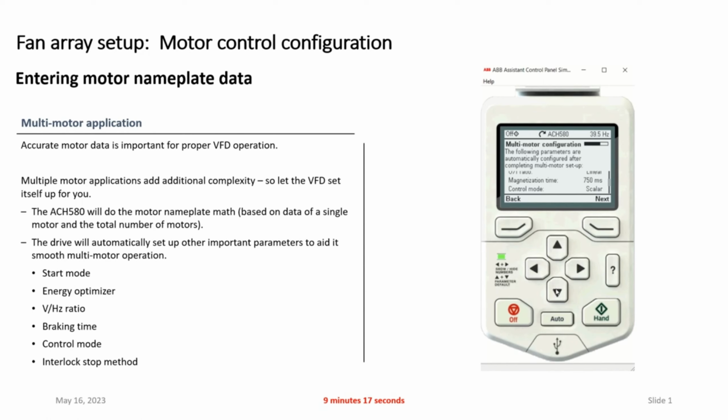It's letting you know that, hey, we're running in scalar mode. There's scalar and vector mode in drives with induction motors. Typically with multiple motors, scalar gives you better control and functionality at the end of the day, and more reliability. And of course, the last is the motor type. We're assuming it's an induction motor with these above settings. If you did not have an induction motor, this is your flag to say, hey, let's take a look, maybe this isn't the right configuration. But a lot of what you're dealing with is going to be induction motors.